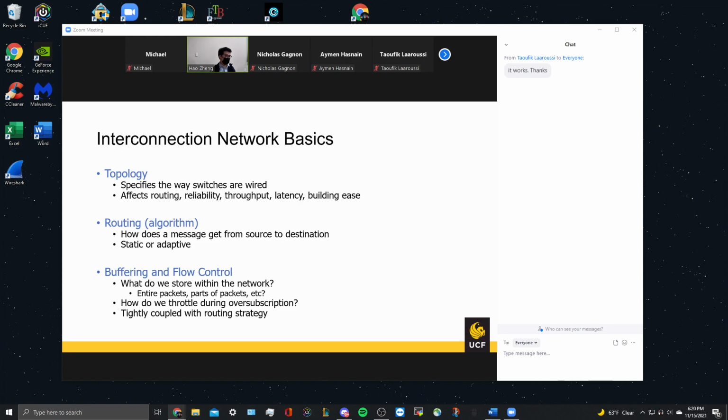So imagine that. What are the key components to achieve the pipeline? What kind of hardware do we implement between different stages? Do you remember that? Yes, the buffer, right? The latch to temporarily store some intermediate results, right? So the same thing for the interconnection network. We need to implement some storage to temporarily store the packets during the transmission, right? To avoid some contentions or other things.